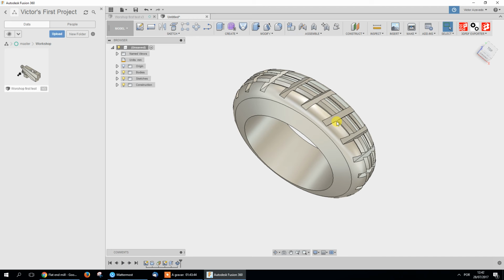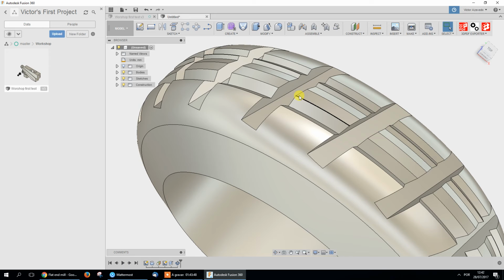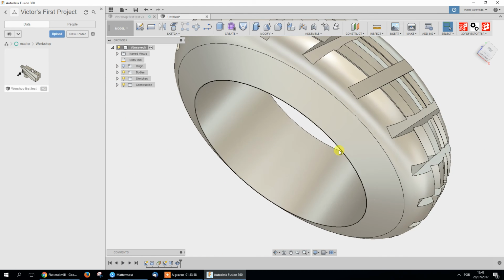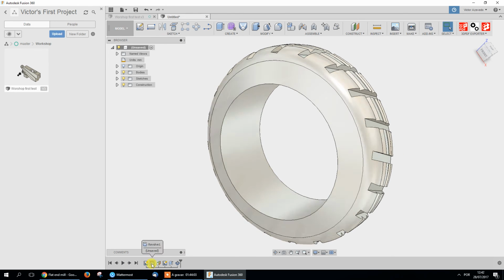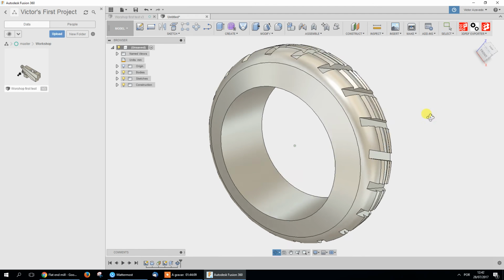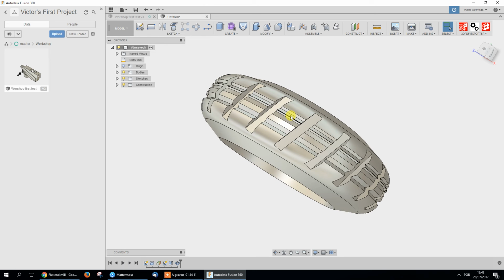I've seen it, and a tire doesn't have these big grooves, it's small ones. You can embed everything with different depths and then choose the features and revolve everything. And in 2 sketches and 2 operations and 1 extra plane, I've made a tire with a lot of features, with a lot of cuts, different designs.